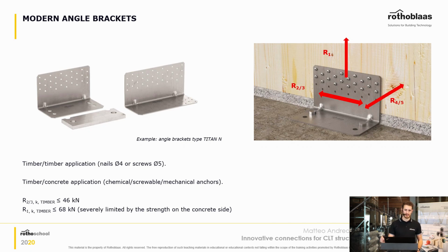So this is a standard connection, and as I was saying before, this in particular is a connection that you can use as a hold down for tension forces, and you can use the same connection as a shear connection for the walls, for example. And we're going to see how that's better.